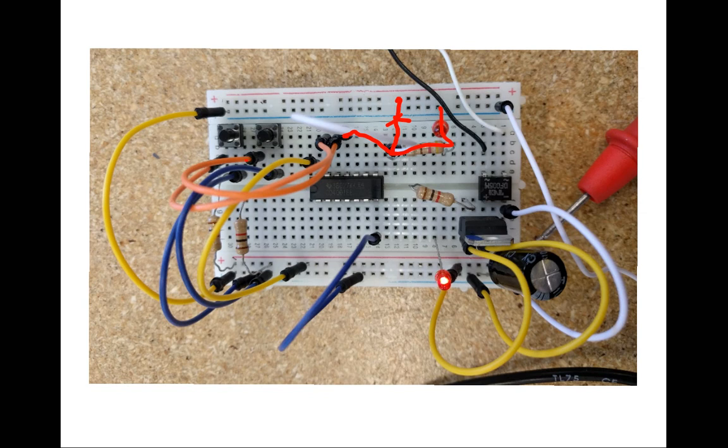The other thing is, I would check with either a voltmeter or a voltage probe. No, your differential voltage probe. By the way, this happens to be the probe of a voltmeter, to just make sure that your switches are running correctly. So measure this point and make sure it is switching between +5 and 0. So that's what you have to do, and I hope you have fun with it. This terminates our video and the conversation.